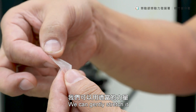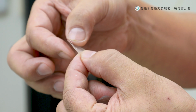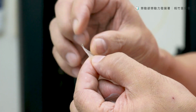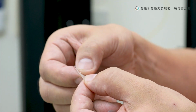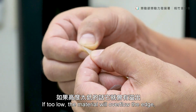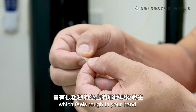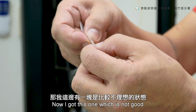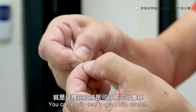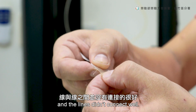We can gently stretch it diagonally, focusing on observing if the lines are connected with the set thickness and the clear edges. If the nozzle is too high, the pieces will fall apart. If too low, the material will overflow the edge, which feels rough in your hand. Now I got this, which is not good. You can easily tear it apart with stretch. This means the nozzle is too high and the lines didn't connect well.